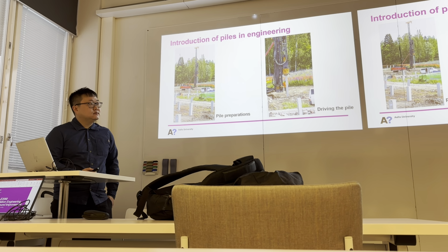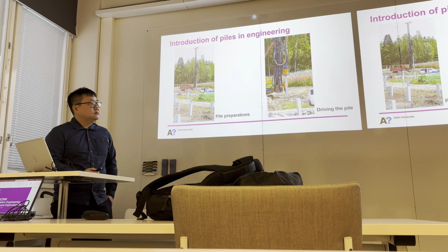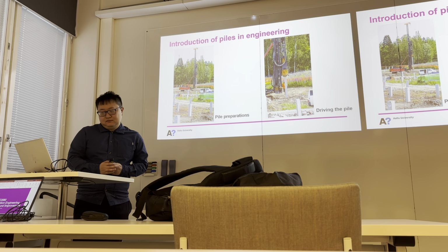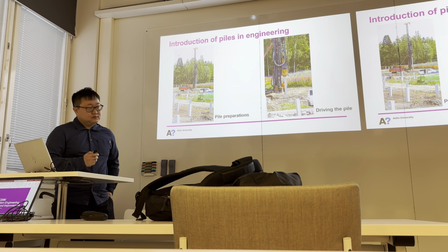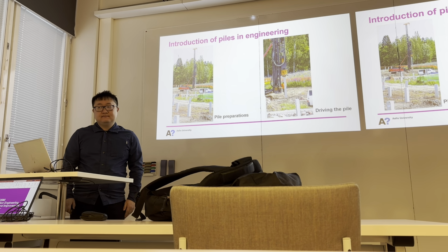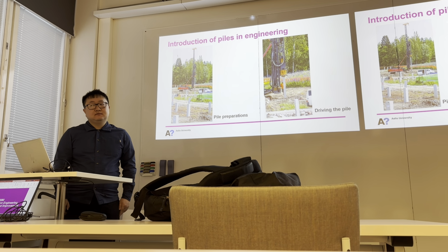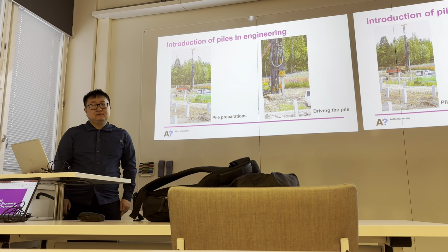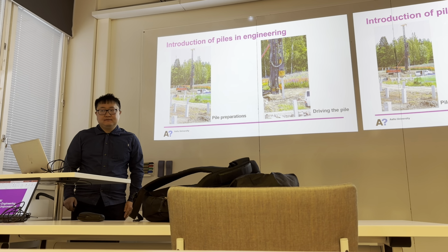I will tell you soon why this is done. Only after the resistance of the soil becomes bigger do they start driving. So the soft layers are penetrated by pushing, and after that comes the driving.